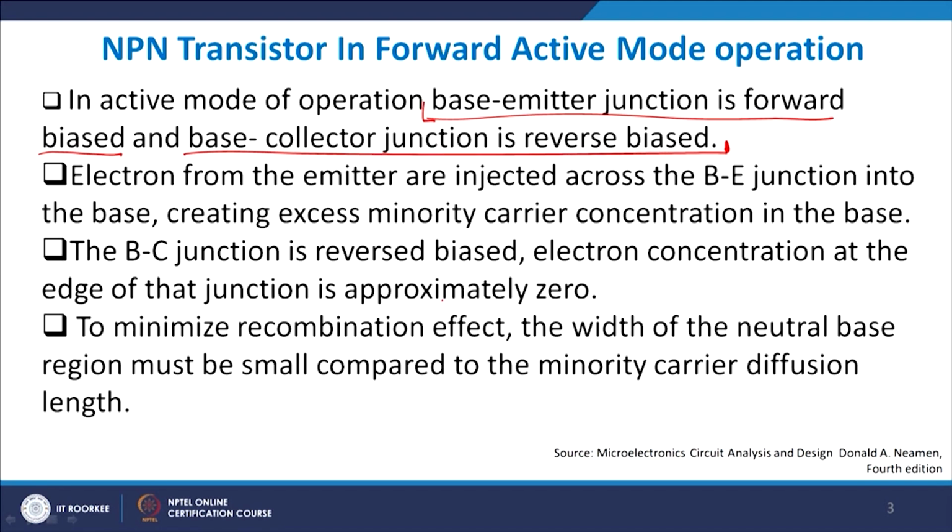Now, one important point which you should note down as far as designing a BJT is concerned, if you remember the previous talk, is that the IS value, the saturation current value, depends upon the cross sectional area of the emitter.